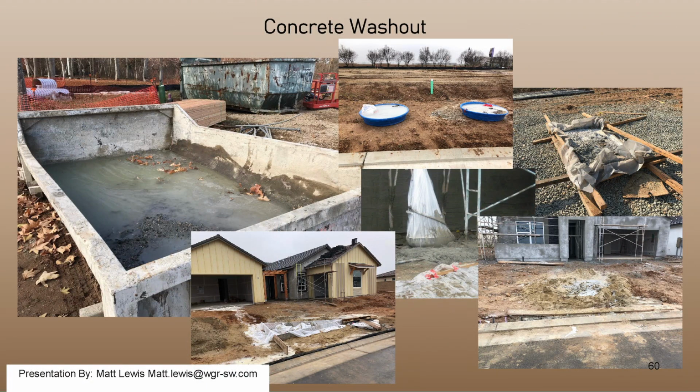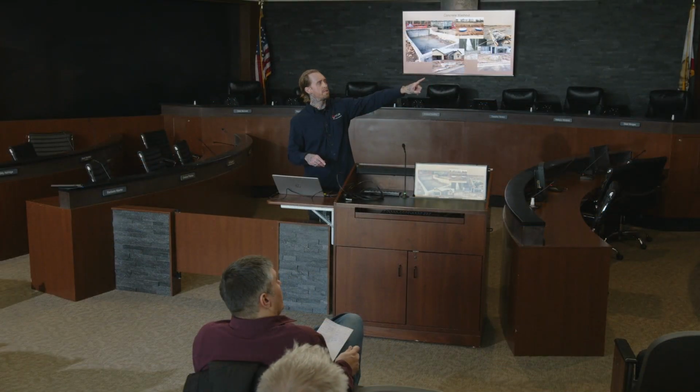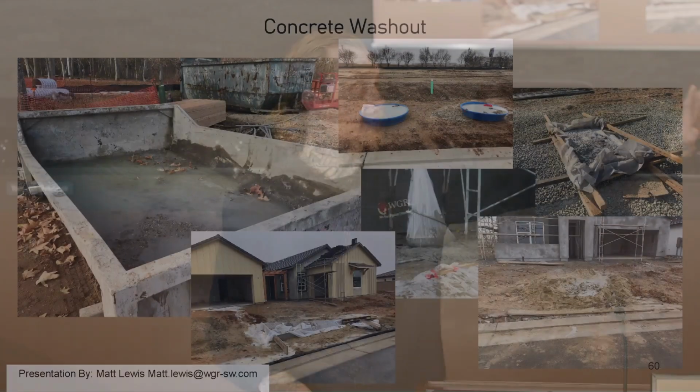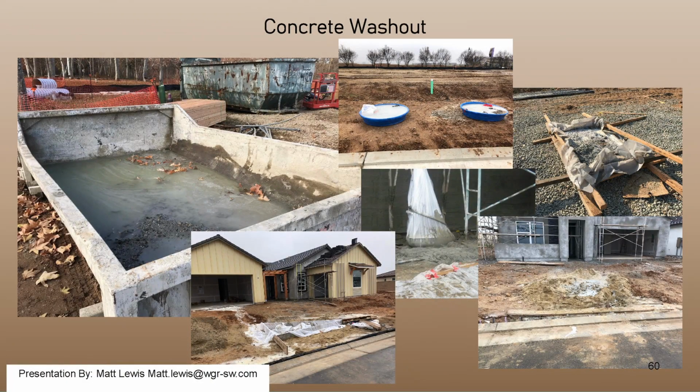But usually what happens is some sort of lame attempt of screwing together 2x4s with sheeted plastic, and they create a Mickey Mouse version of a concrete washout, which, as you can see, generally never works because it usually turns into what's down there in the middle center, where it usually fills up, spills out, and just gets everywhere. So the top left is the best option, but it's the rarest to be used, but it's always the best.